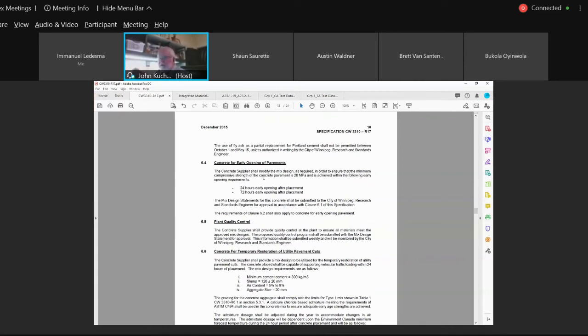Concrete gains strength over time, okay? And we get about 2/3 to 70% within the first 7 days of casting concrete. That's why we test concrete at 7 days typically, and then at 28 days, because if we test concrete at 7 days and we know what the strength is, we can make a fairly accurate prediction that, yeah, we'll have no problems at 28 days. Concrete is designed to meet strength at 28 days. Typically, it's achieved a lot earlier. Okay, but it's at 28 days.